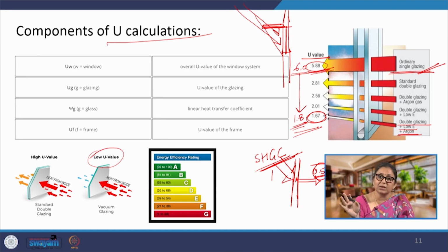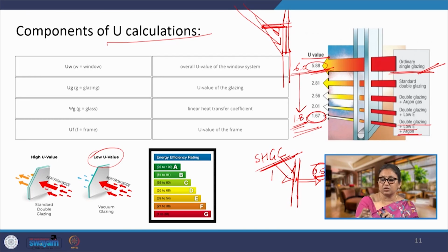So, SHGC becomes immaterial, or we could have multiplication factors, which is how the ECBC, Energy Conservation Building Code, works, and the calculation for the heat that is transmitted inside due to SHGC is calculated. Again, we will calculate the amount of heat that is reduced, but in clear understanding we have to know how and where these shading devices should be provided, of course, along with the selection of material.